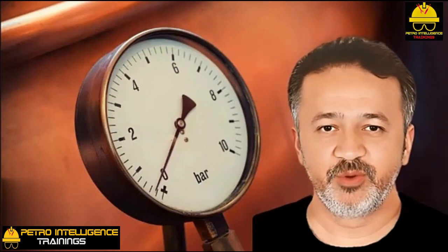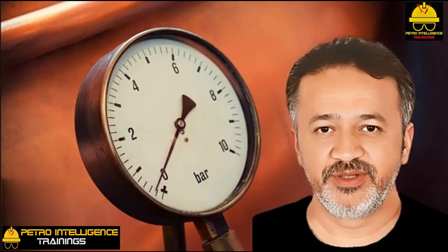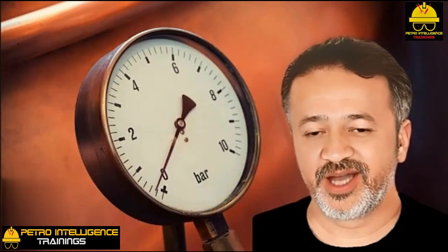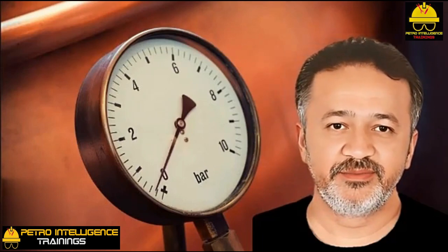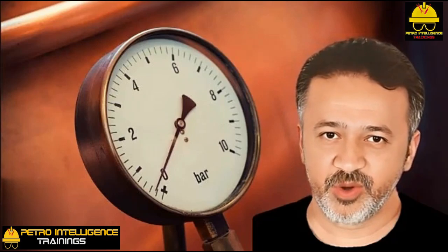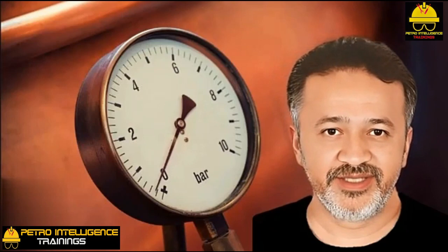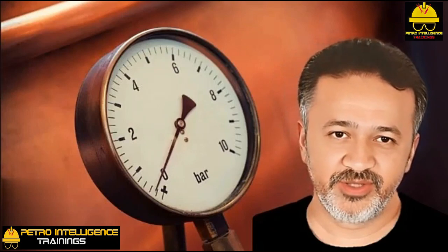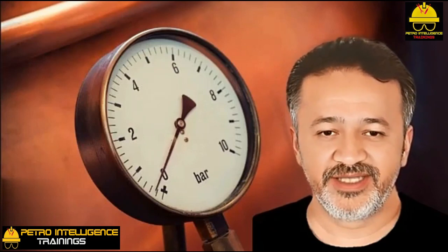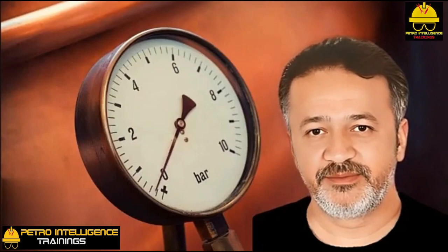How, then, does one determine the actual liquid level in the tower on the basis of the apparent liquid level in the gauge glass? The answer is that there is no answer. It cannot be done. And this statement applies to all other sorts of level measuring instruments, with the exception of radiation devices.